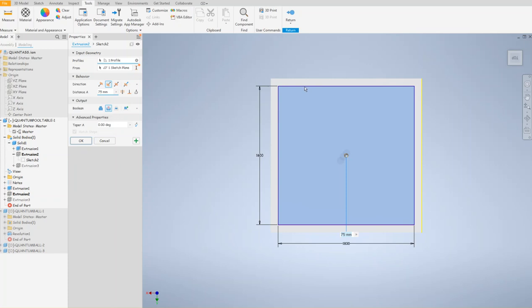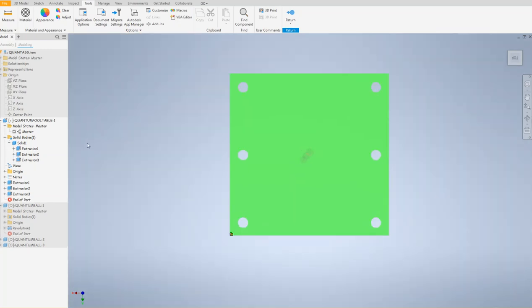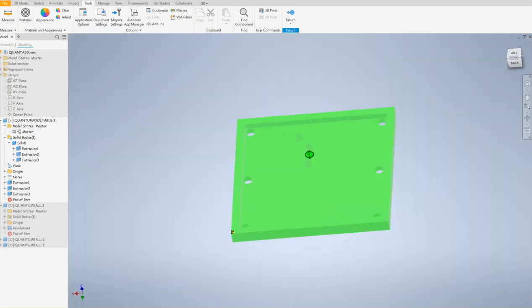We're going to use the subtraction, or negative Boolean cut type of Boolean feature. The extrusion will be downwards, and it's going to be cut type. When you click OK, you're supposed to get a depression like the way it's shown on the screen right now.